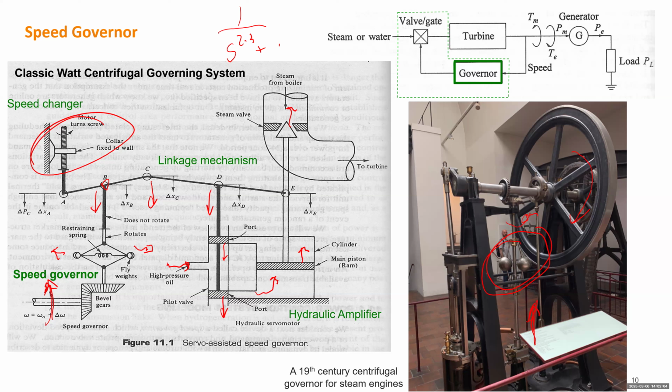If you move that screw up, that will make the entire system operate at lower speed. So this will be the input. Although the value is just the position of the screw and doesn't tell the power, it will influence the power. You can translate it to how much power you want this generator to output.